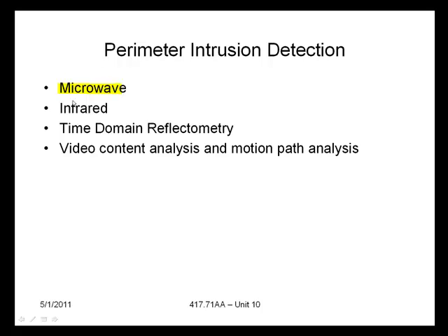Infrared sensors pick up human body heat, so it's great for detecting when someone approaches. Passive sensors detect the heat emitted by animate forms. Active infrared sensors transmit a signal via transmitter and have a reception, or it's an interruption of a beam. It's kind of like crossing the electric eye in the old style offices or services where you cross a beam of light and a little bell goes off telling them that somebody walked into the front lobby. That's the same thing with infrared here. So it can either detect the heat generated by human body temperature, or it can be used as an interruption when some large object interrupts the beam.